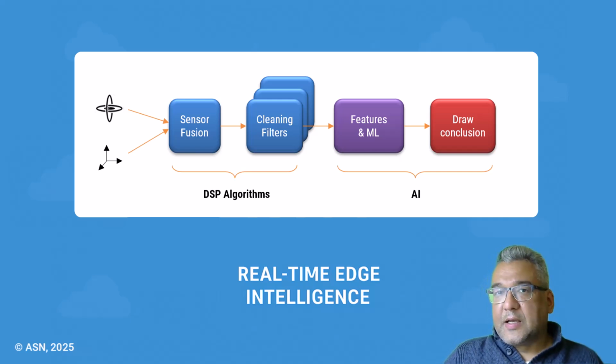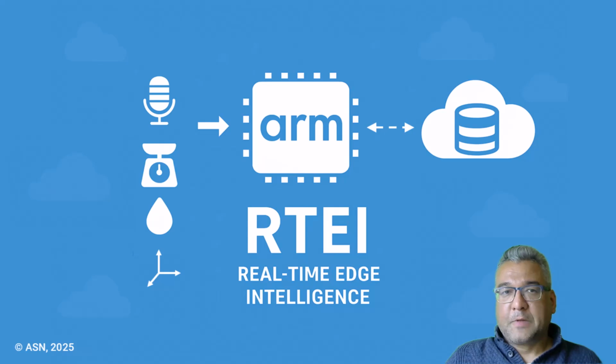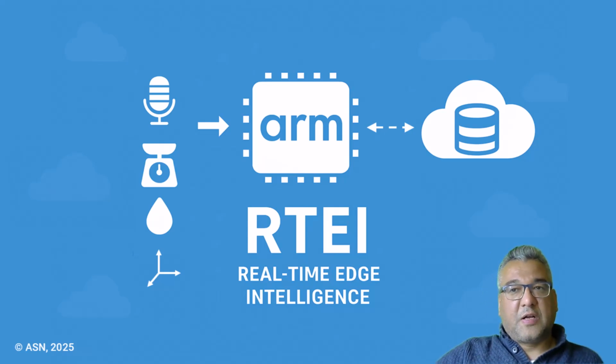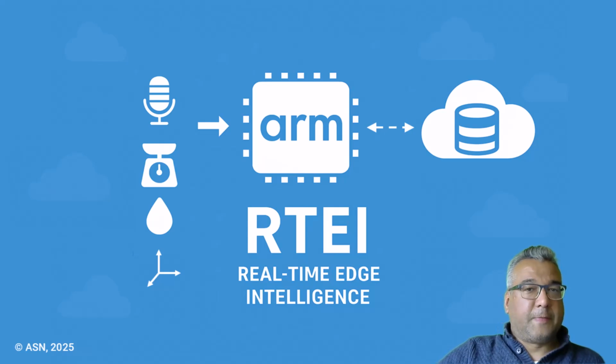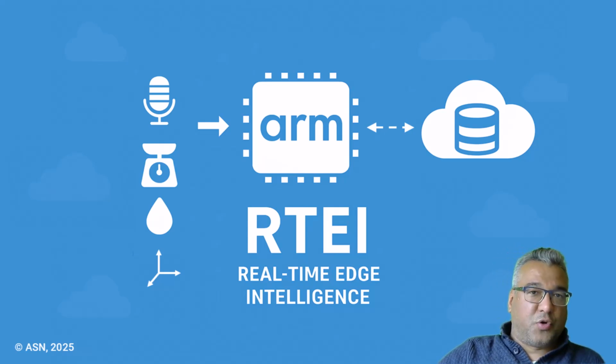Looking at the data cleaning aspect, we can actually make the filtering task somewhat simpler by working with linear acceleration data from our MEMS sensor, whereby gravity and some low-frequency drift are removed by the sensor fusion block. This circumvents the need for a high-pass filter, whose low-frequency cutoff would otherwise introduce massive latency, making the system far less responsive for real-time feedback. However, what remains is high-frequency noise that will reduce the accuracy of our ML model.